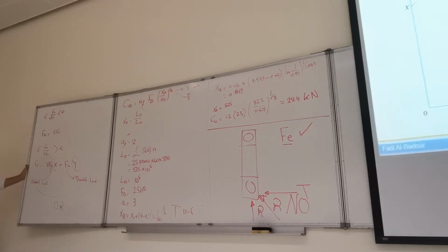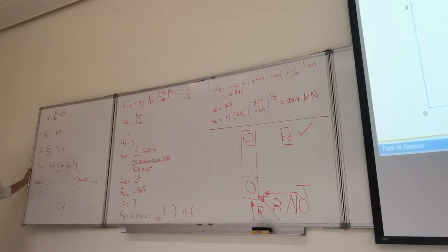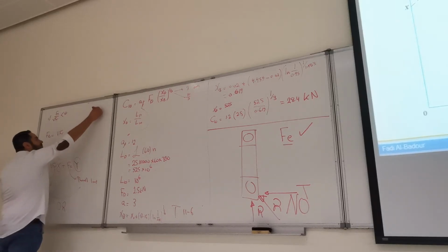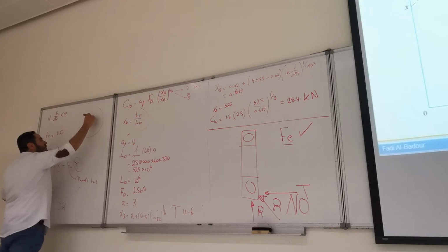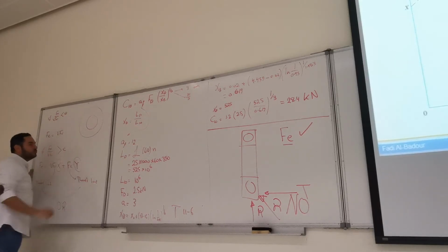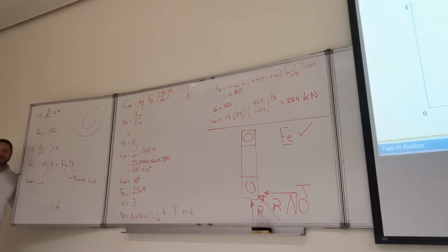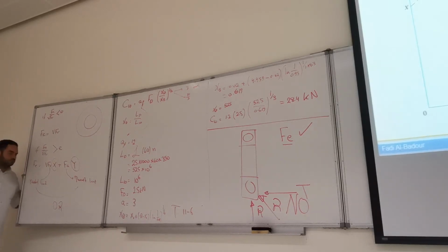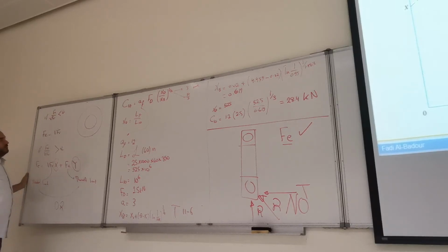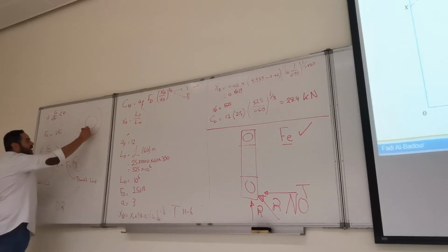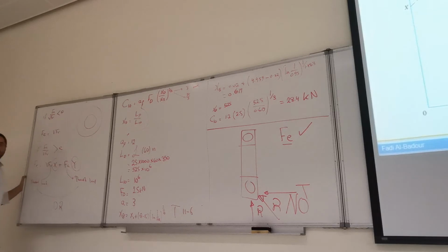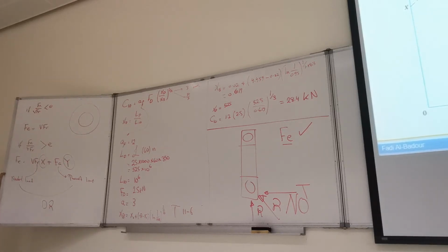Okay, fine. What is V? V is related to the way the bearing is running. Now, if I have a rotating shaft, which part of the bearing rotates? The inner ring. Okay? Fine. If I have an axle and wheel, the outer ring is rotating.